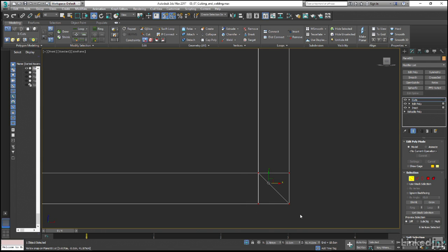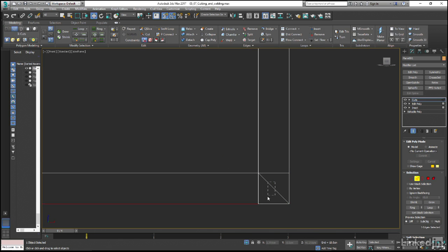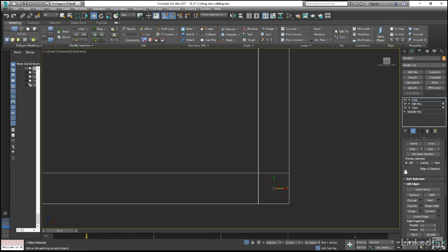Let's then select all of the vertices, shift click on the Weld tool in the vertices panel, and up the threshold value to about 0.2, which, as you can see, tells us that we started the weld operation with 43 vertices, but have only 41 once it is complete, which means we can click OK. Hitting the 2 key to switch to edge mode, I can select the edge running across the square here, and then click the Remove button, which leaves us with the square polygon that we wanted.